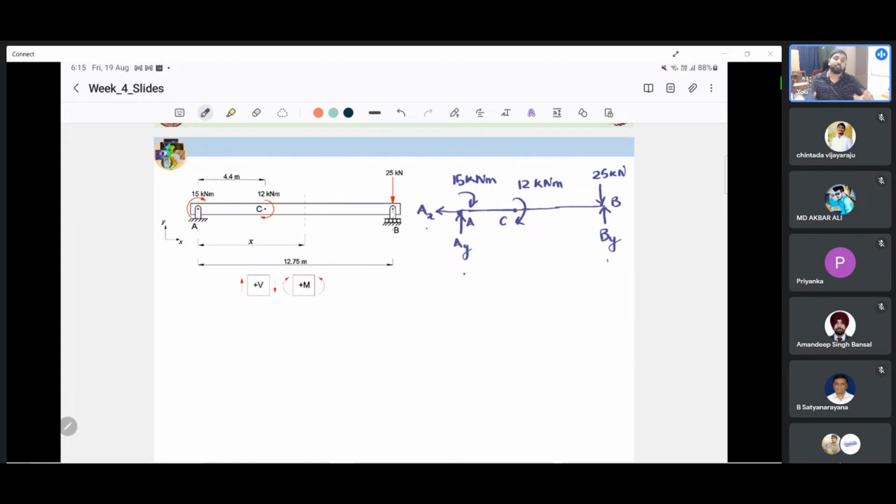We can see that this beam is in static equilibrium. So we have three planar equilibrium equations at our disposal. Let us apply them subsequently, as we did for the truss, in order to calculate the reaction forces. We know that there is no acceleration in the x direction, so the sum of all the forces in the x direction is 0. What are those? Minus AX, because it is pointing in the minus x direction. Are there any other horizontal forces applied? No. So this equals 0, which gives us AX equal to 0.